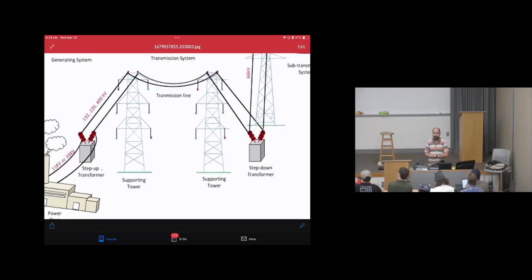Then when we transmit the power, why do we need to add a neutral? We don't need to. We can remove the neutral wire and transmit the power for high voltages, extra high voltages, or even medium voltages as only A, B, C without a neutral. And that's what's happening in real life. We can save more money by avoiding the neutral, because transmitting the power from A to B without any disconnection for 100 miles, 200 miles, I can save more money by removing one conductor. That's one advantage, right?